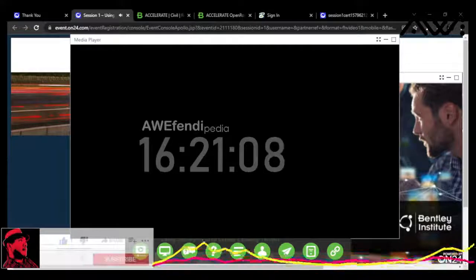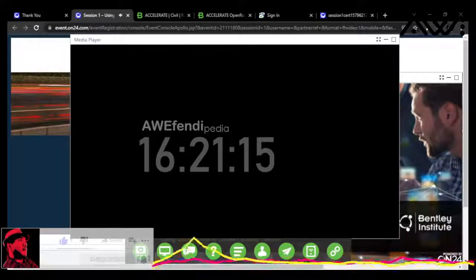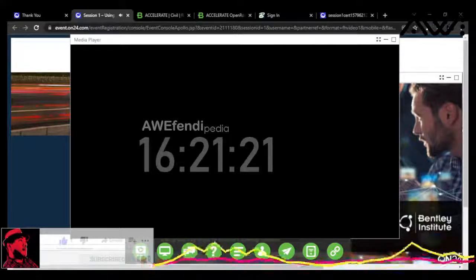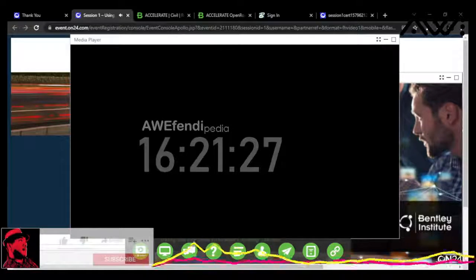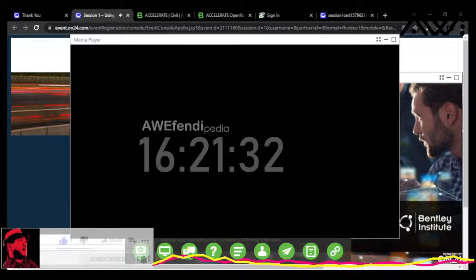When we hit add there. So I'm using join point now, but if you wanted to use control codes to draw some circular features, or again do some of the tape distance or rectangular measurements, you could do that here. You can code those out in the field, and in the raw data, when it brings it in, it'll assign these control codes automatically. But again, I'm just using join point.